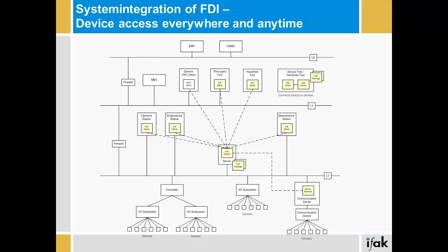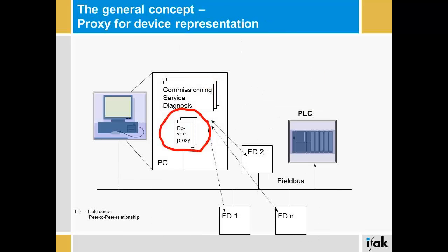I want to give some background on which technology is behind this. The technology says that for each individual device, we want to have an individual access to the functions and to the parameters. This would mean that there is an application in a commissioning tool, in a service tool, and a diagnosis tool, and this application has to be adapted to the individual functions and parameters of individual devices. The idea is to have a representation of each device in this tool, so that we have a general multifunctional tool which gets the right functions by this representation of the field device, and this can be seen as a device proxy. This proxy is a representation, and we can integrate this proxy in these tools, and then we can read and write and speak individually to each individual device.